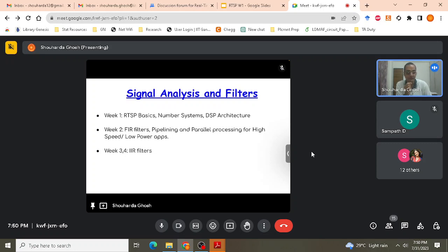So we will never use floating point architectures in places where there is a need for low energy, low power implementation. Also, these are not used in places where you have area constraints. Like I told in the pacemaker case, you also have hearing aids. There are some limitations on your chip sizes, and that chip size limitation also forces you to put some restriction on the kind of units that you can use in your system. But you can use it in a processor. Why? It's a general processing unit.